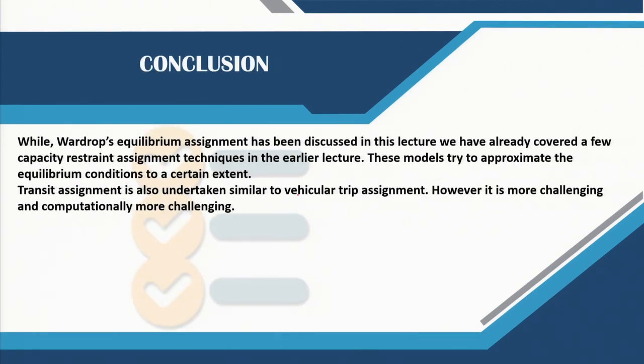And to conclude, while Wardrop's equilibrium assignment has been discussed in this lecture, we have already covered a few capacity restraint assignment techniques in the earlier lecture, and these models try to approximate the equilibrium conditions to a certain extent. But if we want to go into more advanced assignment techniques, we have to look into the equilibrium assignment techniques compared to the capacity restraint assignments, and then we can also look into SUE techniques as well.